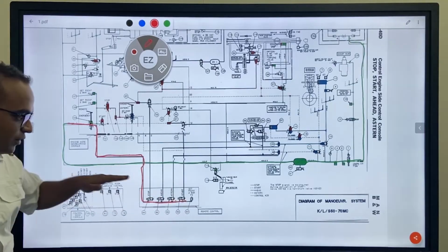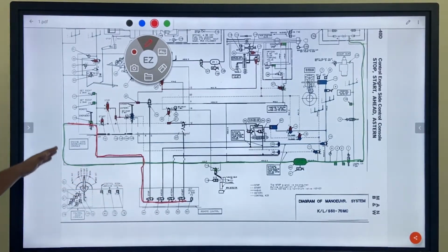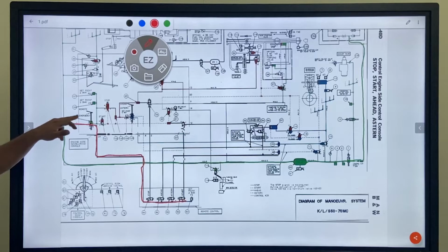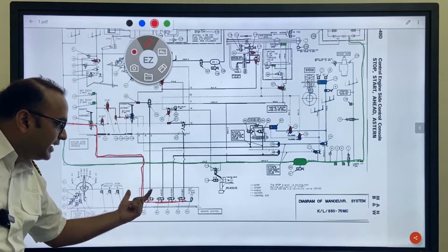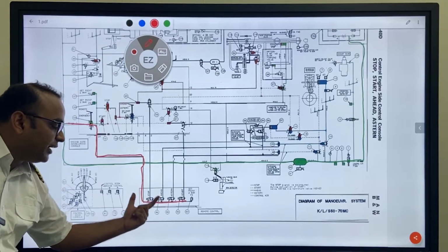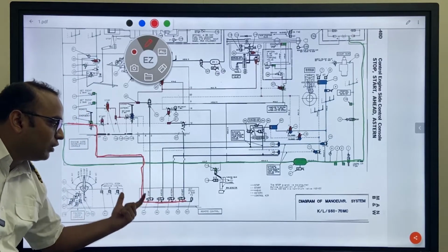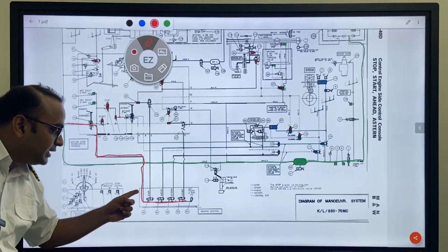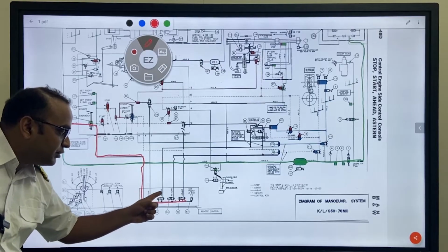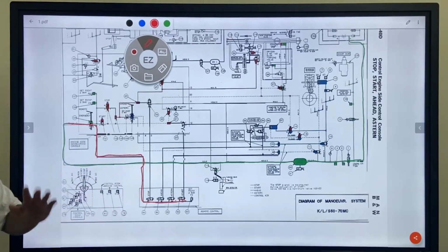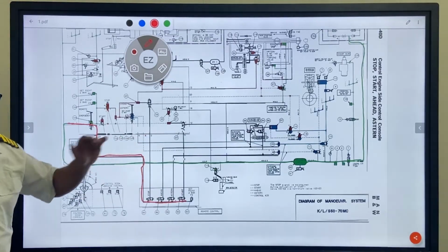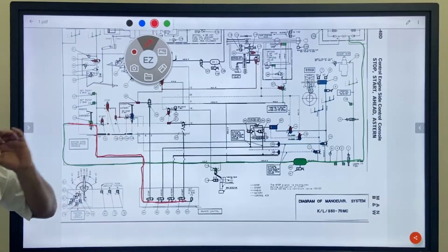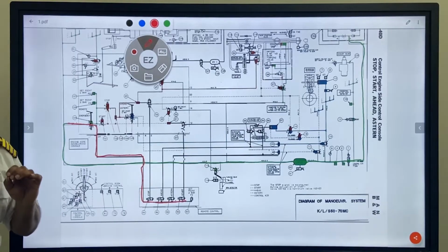The control air, which has come via valve number 100, the selector switch, came down and is waiting at these 4 solenoid operated direction control valves. You can see the names: stop solenoid, ahead solenoid, astern and start. The air is right now waiting to go up, but it is waiting for some kind of indication, right?